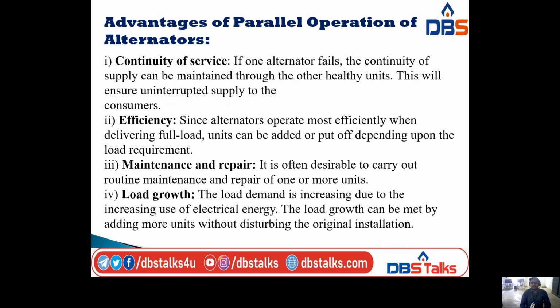And advantages of parallel operation of alternators. We have so many advantages. Of those, we have taken four. The first advantage is continuity of service. Continuity of service means if one alternator fails, the continuity of supply can be maintained through the other healthy units. So this will ensure uninterrupted supply to the consumers.